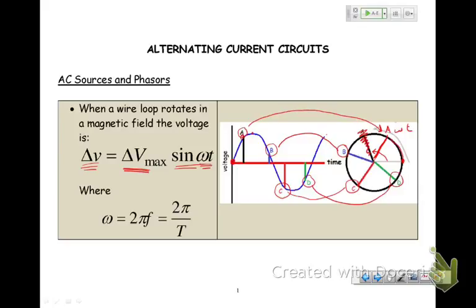Any point on this can be mapped to a point on my phasor diagram. So this is my phasor diagram, and this is my oscilloscope trace. So, boom. Okay. And because it's a simple harmonic motion, it follows a cosine or a sine relationship. And because we decided to start off over here, rather than being 90 degrees to that, we have a sine version of it rather than a cosine version of it. Yeah? Just the way we drew our diagram.